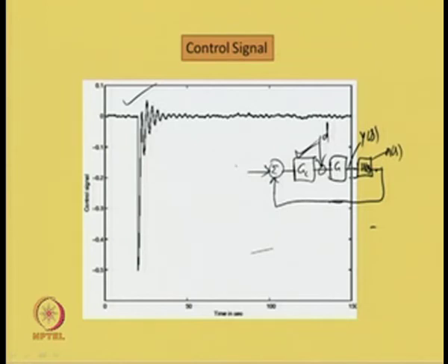satisfactory closed loop performances. In place of injecting or putting a reference filter in the reference path, one can put a noise filter in the feedback path. That is what we have done. So, putting a noise filter of the form TFs plus 1 in the feedback path, still we are able to provide a 2 degree of freedom controller to the structure somehow.